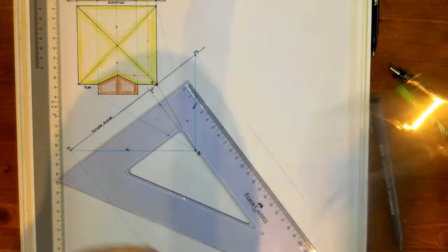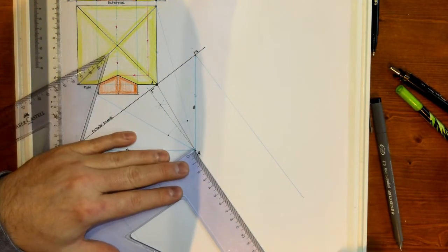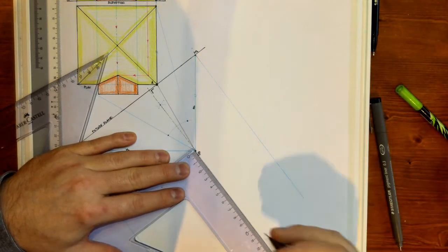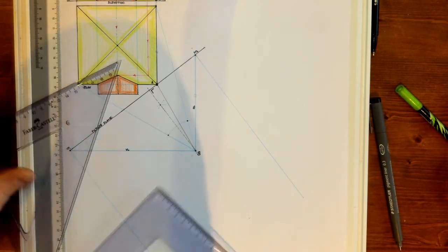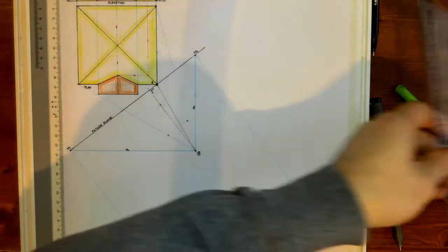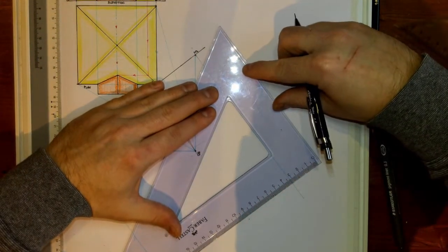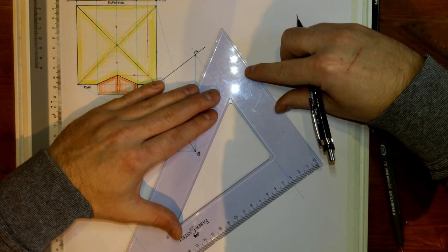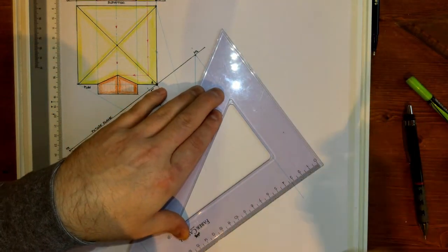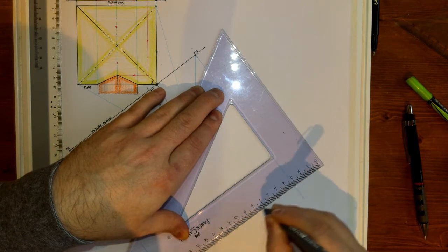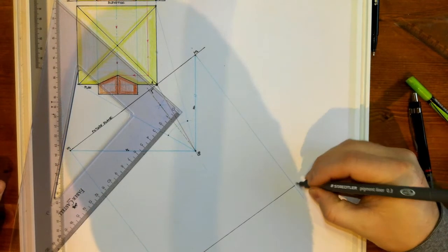Now, if you want, and don't project S down there at the moment, you can just roughly make a dot from S, just mark 90. Okay, it doesn't have to be perfect, but what I'm going to do there now is line in my set square, inside line in line with the vanishing line, and the outside line in line with the point I marked just a moment ago. I'm going to draw my ground line, and I'll draw that ground line heavy, and I'll put the note in there, ground line.